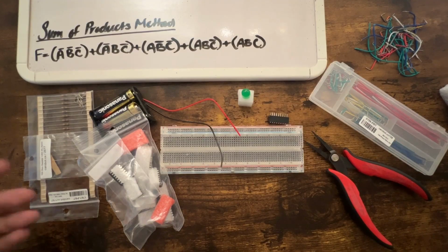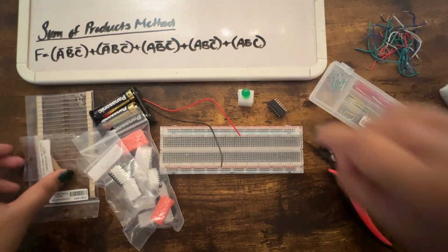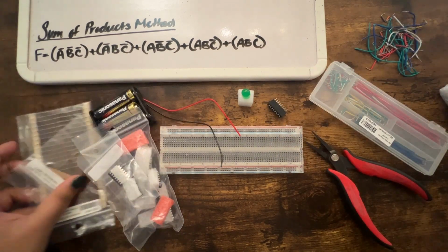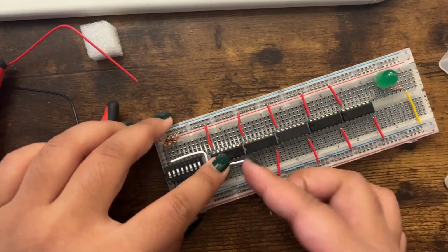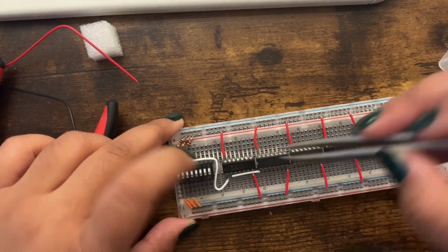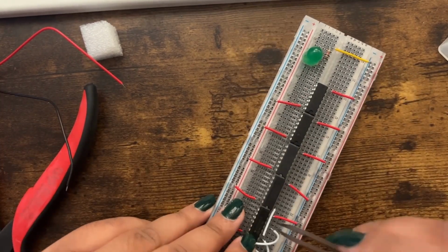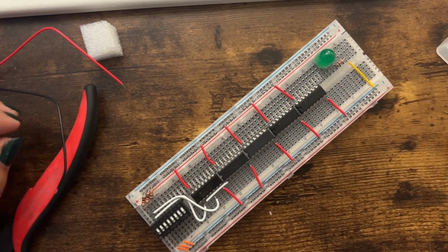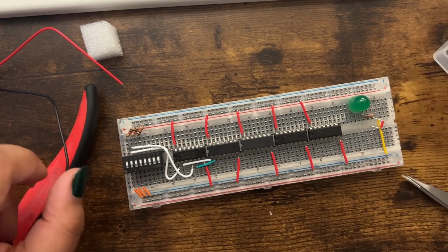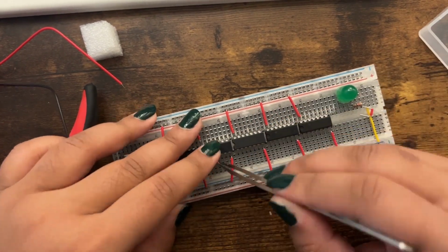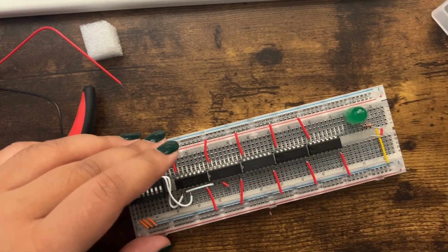First, we're going to build the sum of products function, so we're going to need our usual suspects. We'll need a battery pack, an LED, a switch, some resistors, some gates, lots of them in this case, and some bendy wires. So I've already set up my power connections and I've laid everything down. So what you're seeing from left to right is a NOT gate, two AND gates, and then two OR gates. And then what you're seeing is I'm taking the inputs and running them through the NOT gates and then running the outputs from the NOT gates into the inputs of the AND gates.